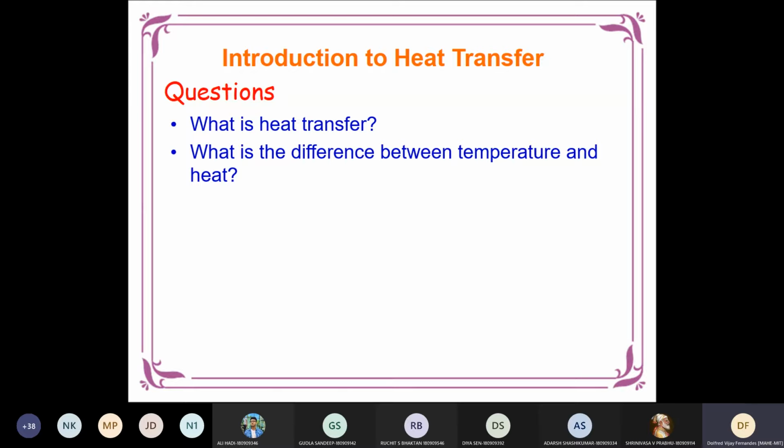Yes, you answered the question exactly the opposite way. Temperature signifies the amount of energy stored in an object or a substance, whereas heat is energy in transit. If everywhere is the same temperature, we cannot estimate any transfer of heat, because there is no heat flow.